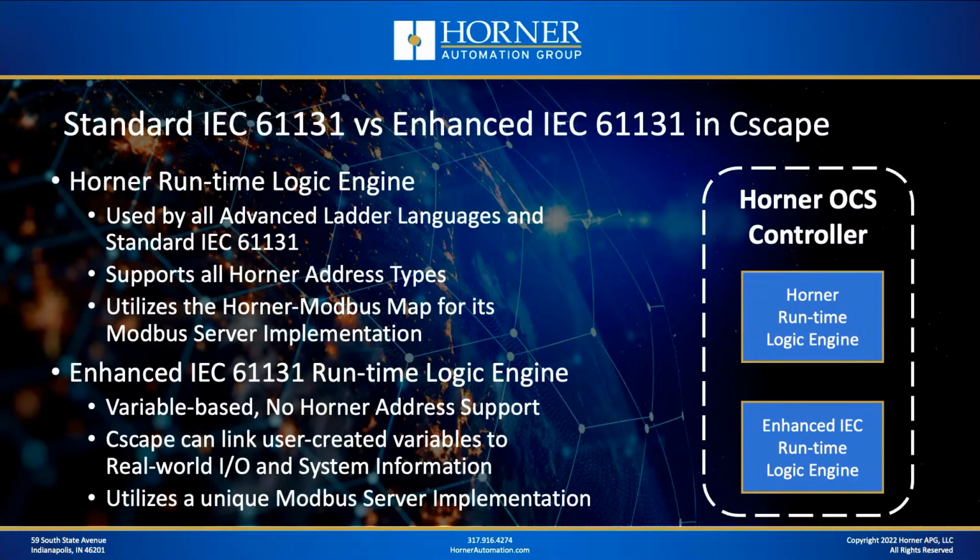However, when we talk about the enhanced IEC runtime engine, it's variable-based, and there is no Horner address support, certainly not for internals. There's no such thing as an R or an M or a T in enhanced IEC. Now, we still have I's, AI's, AQ's, etc., and S's and SR's for mapping purposes. So you can take your variables and map them over to real-world I/O and system bits, but that's the extent of it. Because we don't have all these Horner address types, we can't just use the Horner to Modbus map. We have to do something unique, and we'll cover that a little bit later.